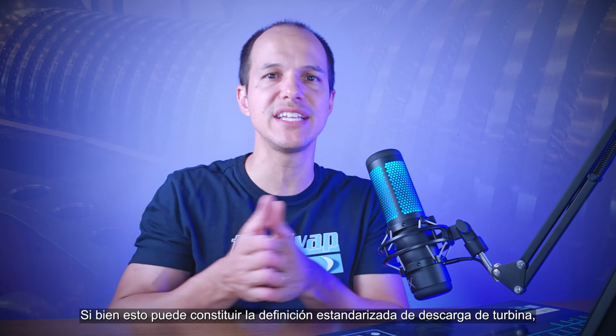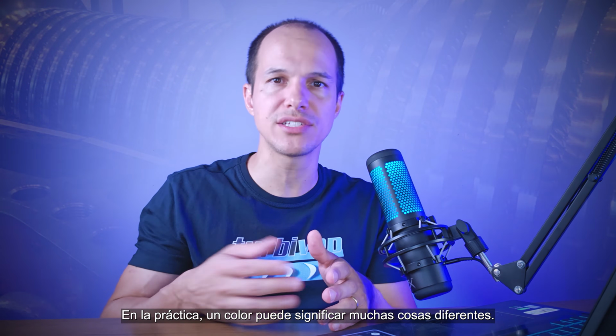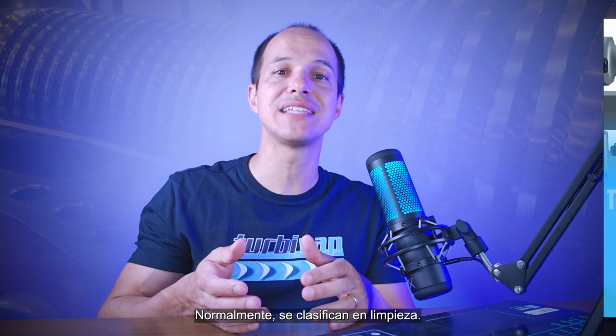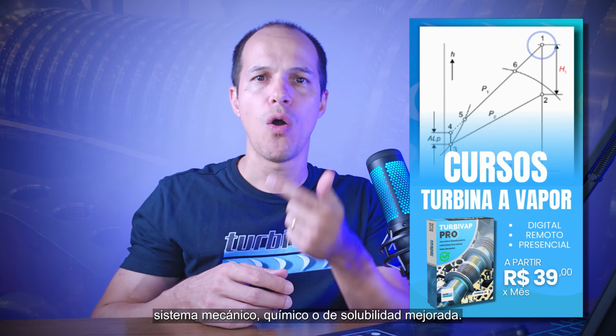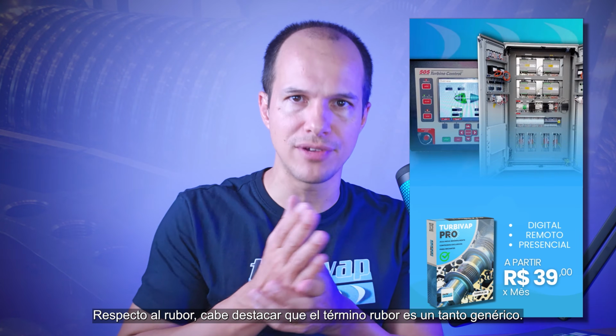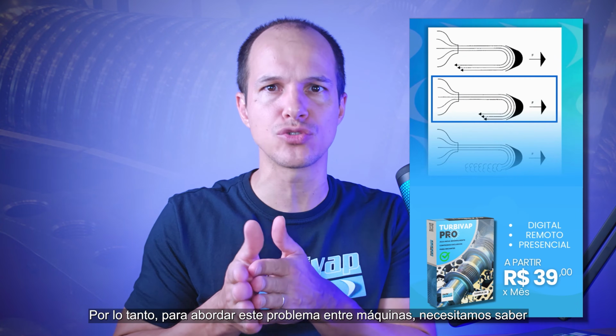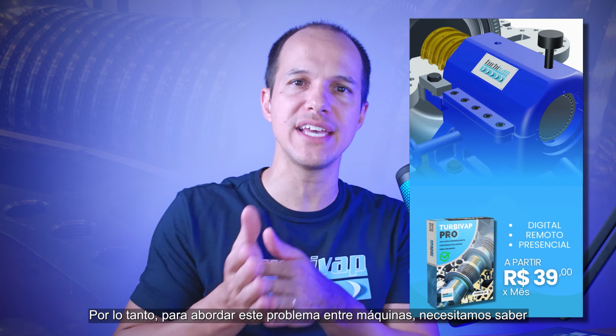For hydroelectric power plants, flushing is defined as circulation of liquid through a lubrication system or component when the turbine is not operating, to remove contaminants. While this may constitute the standardized definition of a turbine flush, in practice, a flushing can mean many different things. Typically, they are categorized as cleaning, mechanical, chemical, or enhanced solubility systems.